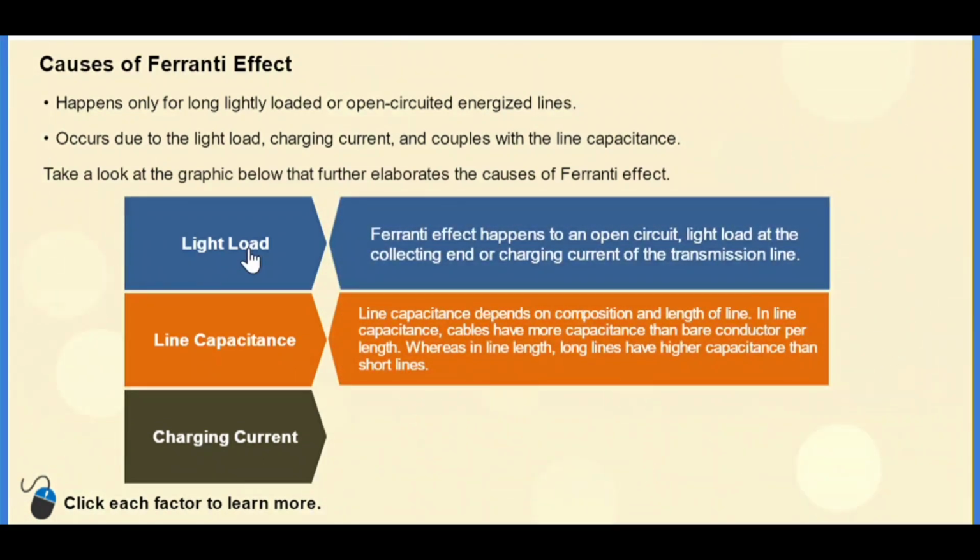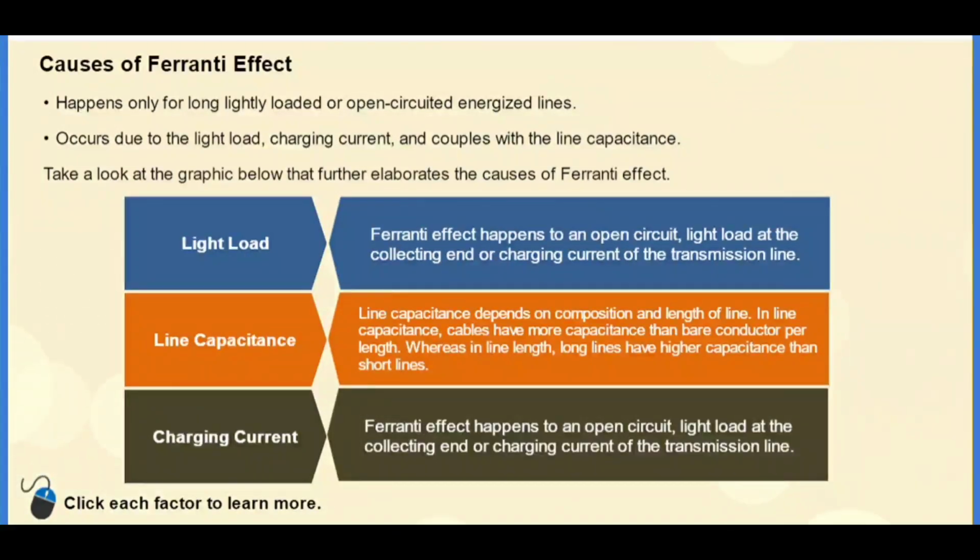Ferranti effect depends on an open circuit and light load at the collecting end. In line capacitance, or charging current, cables have more capacitance than bare conductors per length, whereas in line length, long lines have higher capacitance than short lines. Charging current becomes more important as load current decreases, and it increases with the voltage of the system given the similar capacitive charge.